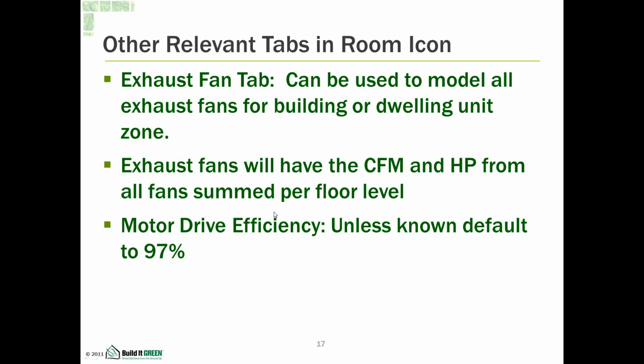So the motor drive efficiency, I think the default is 97%. And unless you pull apart the exhaust fan, you're not going to really know what the motor efficiency is. So I would just default to the 97%.